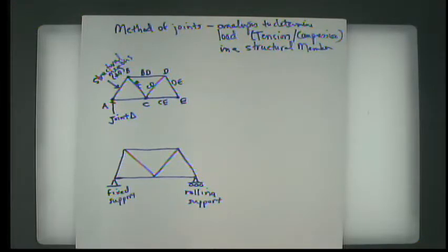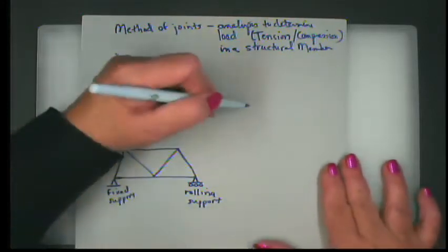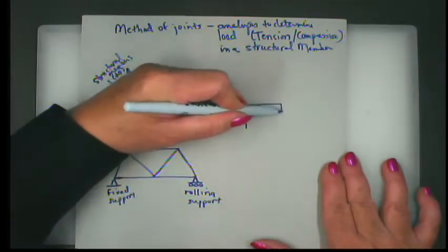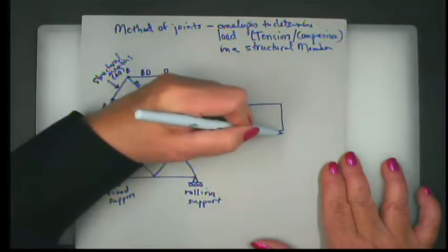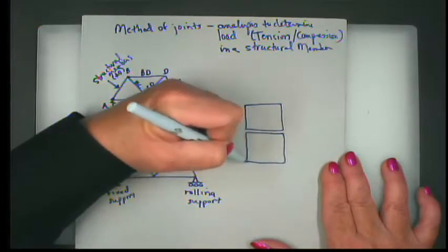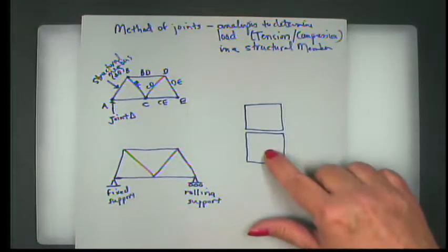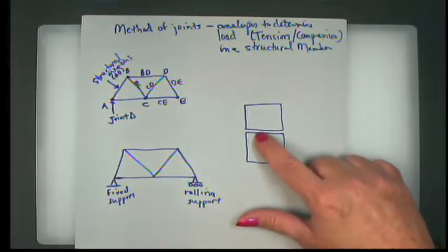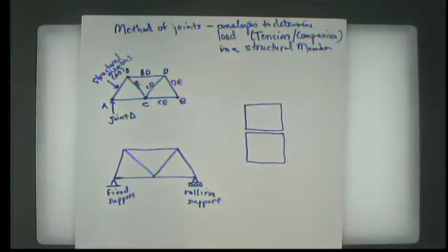Now, a really easy example of this, something you've probably seen, is if you have ever laid a sidewalk or walked down a street. Generally speaking, the concrete of the sidewalk, or even if it's bricks or whatever, has these little gaps in between, and those are called expansion joints. If the expansion joints aren't present, what can happen to the sidewalk over a very cold winter or a very hot summer? Yeah, it buckles up. Yeah, and so you get these whoop-de-doos when you're walking down the streets in Powell. Some of them are like that, I know.